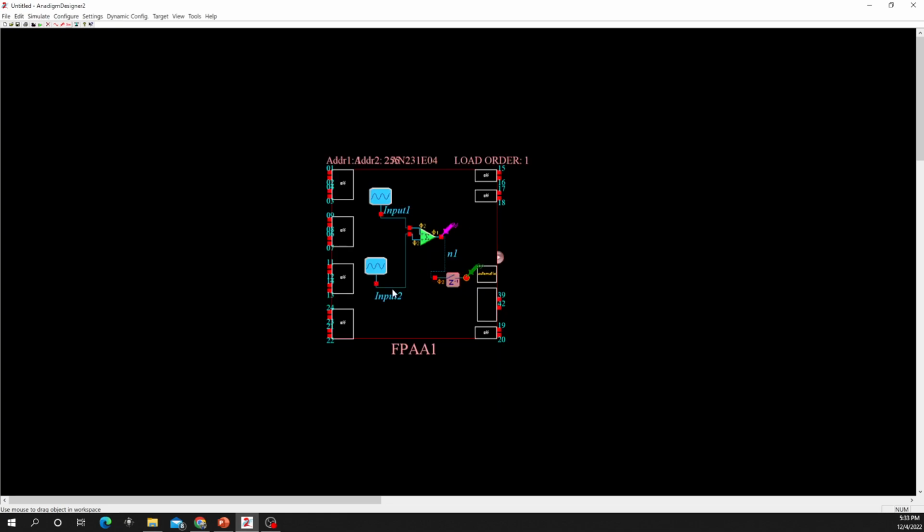So whenever it becomes a dashed line, that means this general warning or phase mismatch. While when you look at those two sinusoid function generators, you didn't see any phase assigned to the output. Whenever this happens, that means those modules work with both phase one and phase two. It doesn't really matter which phase. It's similar with the sample and hold, which also didn't give you an output phase, so it can work with both phase one and phase two.